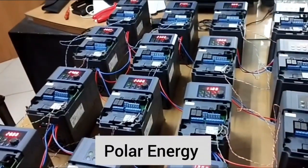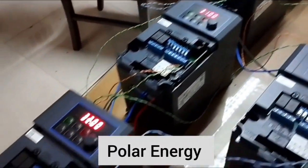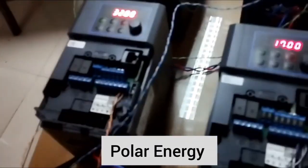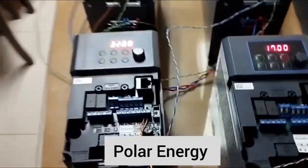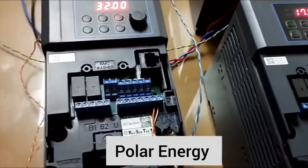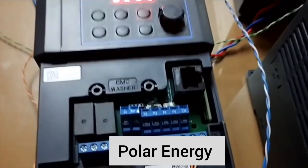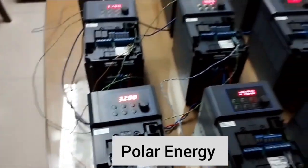We will keep following this exact same process for each subsequent row, eventually reaching station 17, which leads us all the way to our very last inverter, which is designated as station 32. This means that the station address for this inverter is set to 32. To manage the entire system effectively, we've assigned unique station addresses ranging from 1 all the way up to 32 to each of these individual inverters.